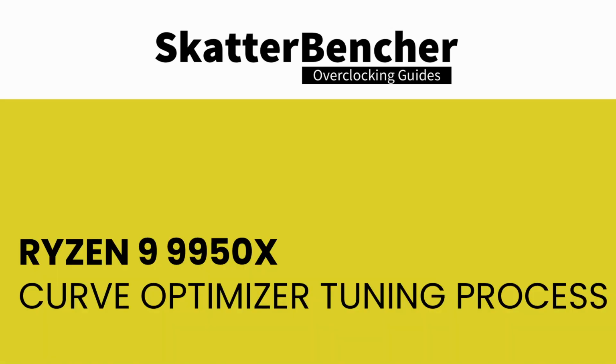The manual tuning process for Curve Optimizer can become quite convoluted because it spans a very wide range of workloads, going from light single-threaded workloads all the way to heavy all-core workloads. Furthermore, on a dual CCD chip, we also have to tune two VF curves at the same time.